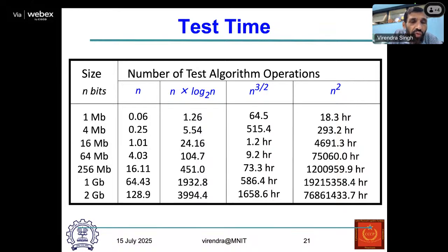Because this is a regular array, I can test this particular memory by simply doing some tasks with the memory element. Because it does limited functionality, storing 0, storing 1, transition from 0 to 1 or 1 to 0, these are the operations it does.